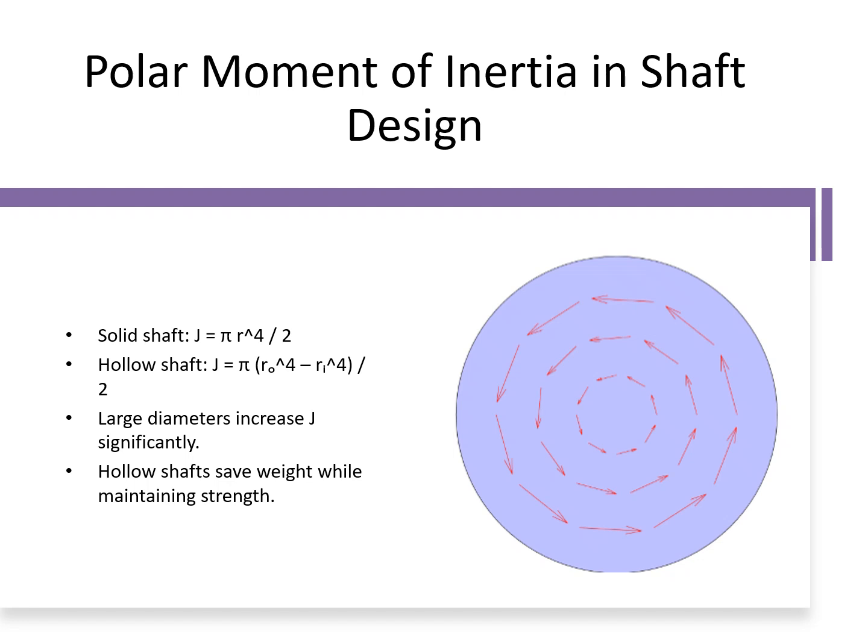Hollow shafts save weight while maintaining the max stress, and even sometimes more max stress, because as we can see, the vectors just shown on this picture on the right are a lot smaller. So there's almost a waste of space in the center of this cylindrical shaft.